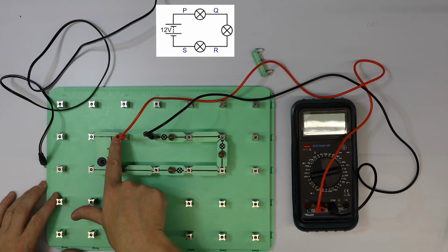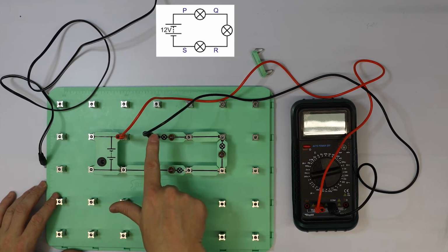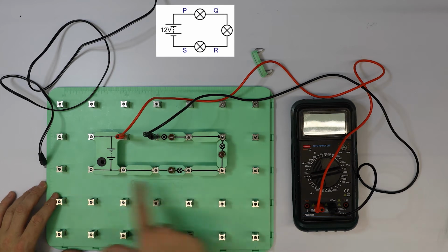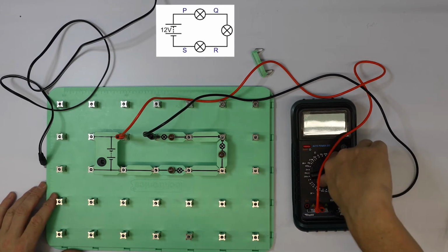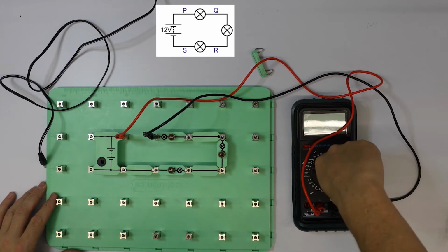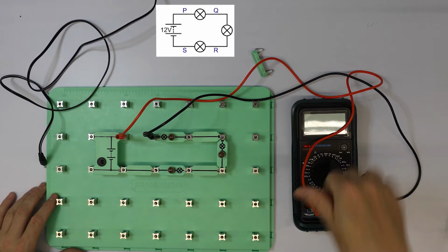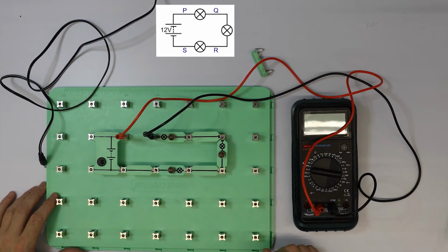So here, the current's flowing from this point. It's flowing through the multimeter, coming back here, and then flowing through these bulbs and around the circuit. So there's no chance that there's going to be a significantly high current here. So what we can then do is we need to set our current value to something meaningful. So what I'm going to do is set it at something like 2 milliamps, see what result I get and whether I have to change that range in order to increase the accuracy of the result.